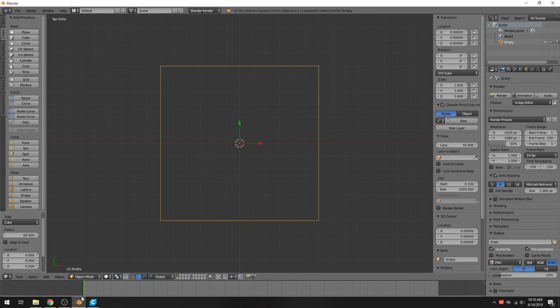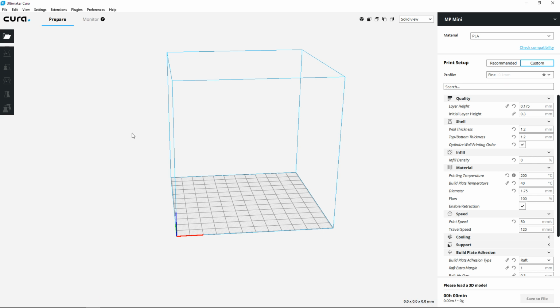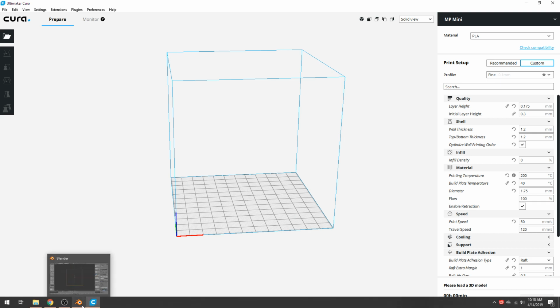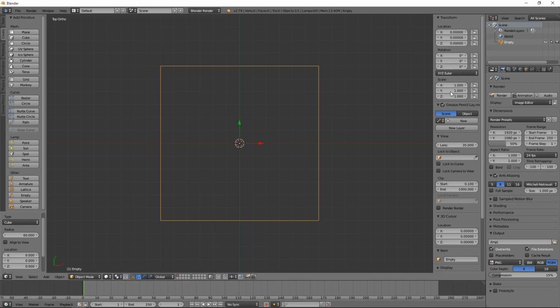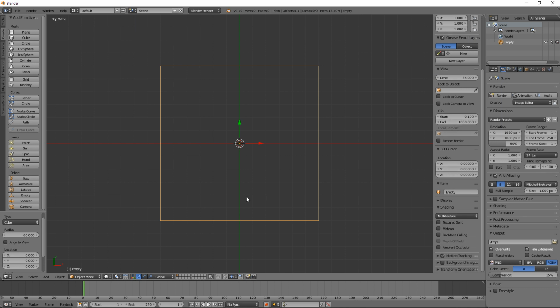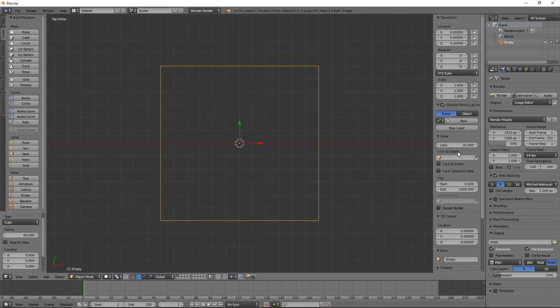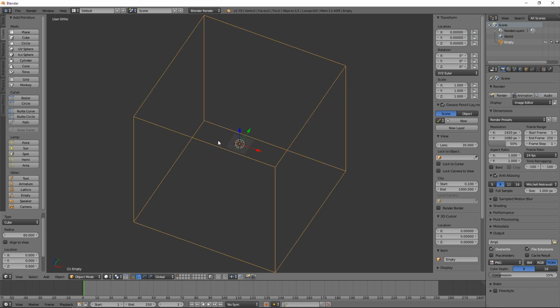Fun fact, if you were to jump over here to Cura, careful, it's about to get bright, and import anything that you build just by default, it'll be a tiny little thing in the middle of the space. So watch your sizing. That's why I had you bring up that numeric side panel over here. Pardon me. So there we go. Now we've got this guy to the correct size. Now it's 120 millimeters, and I'll go ahead and orbit around here, show you that.